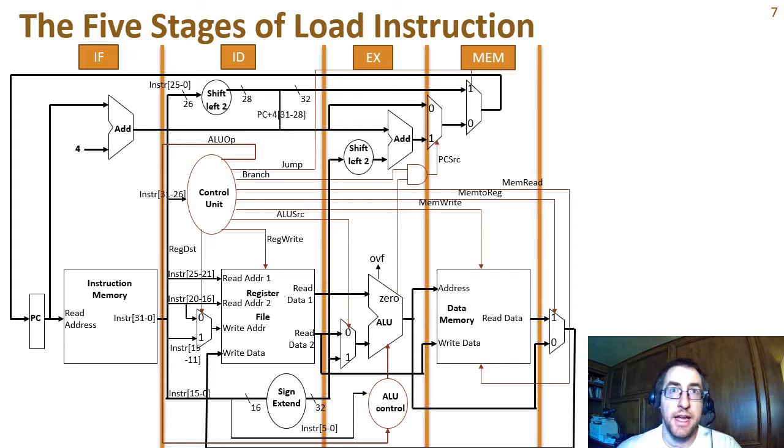Then the data memory access is in the memory stage, mem. And then finally, the register write is in the write back stage. And you'll notice that the write back stage actually also includes the register file logically. We also place some components in parallel to those major components, but those accesses are overlapped with the major components' access, which dominates the critical path of each of these stages.